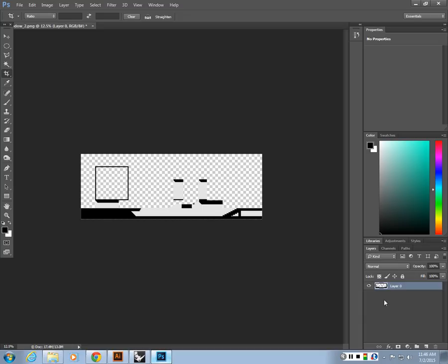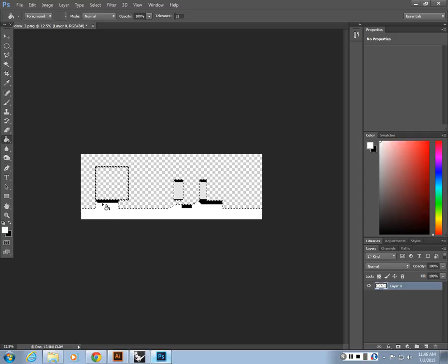And I'll just show you quickly how to do that since I use this one. I'm going to hold Control and click on this image on my layer tab in Photoshop. It will select all the pixels, all the active pixels of this image. And then you can either use brush or there should be a paint bucket tool. Under gradient tool, if you click hold, there's paint bucket tool. And then you want to switch to white. And then paint bucket everywhere.